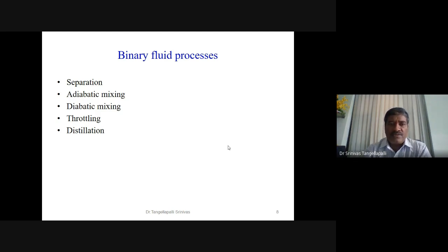For industrial use like cold storage, there is no issue. And also the materials we have to select carefully, as it is more corrosive for copper and its alloys, bronze, such materials. That family we can't use, even for bearings, with this ammonia related working fluid.